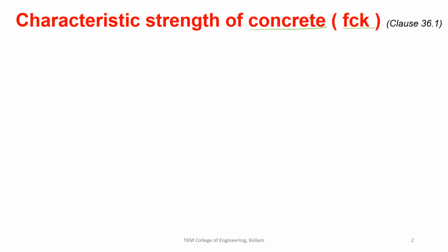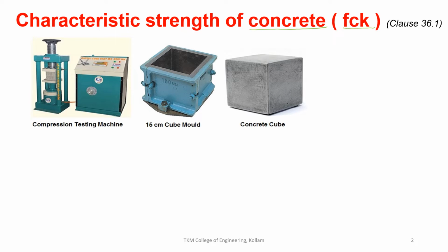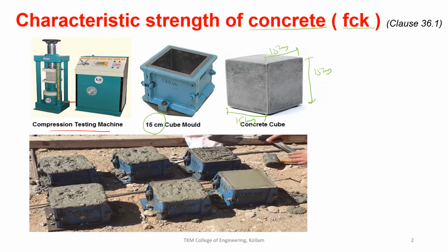What we do here is cast a 15 centimeter cube of concrete. That is, the concrete will have a size of 15 centimeter by 15 centimeter by 15 centimeter. The concrete will be cast and tested in a compression testing machine. This will be conducted on site as well.